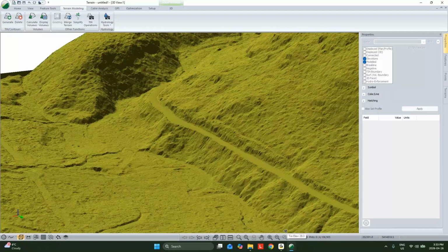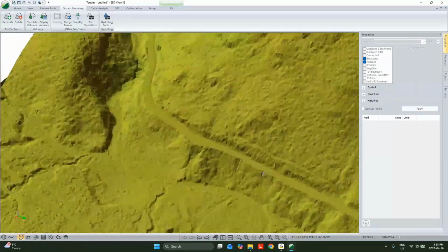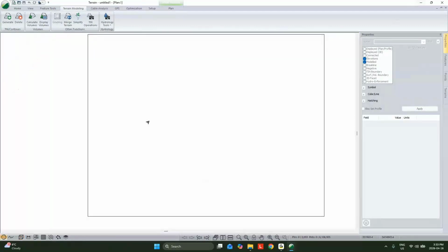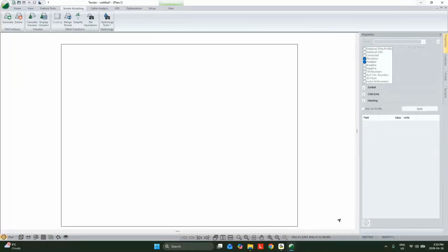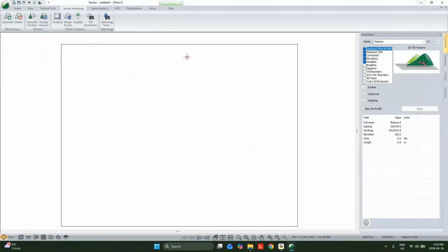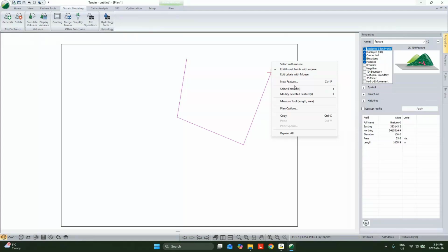Now, aside from that, these big data formats are not all equal, so let's do some thinning. Right off the bat, we've already brought in the LiDAR data with our 6 million points. If I had brought that in and decided I wanted to thin based off of a polygon, I could just draw a feature in and say I want my surface data to be included within this box.